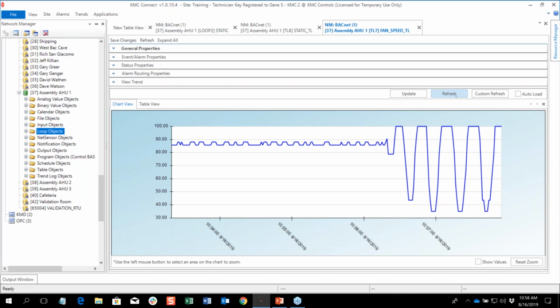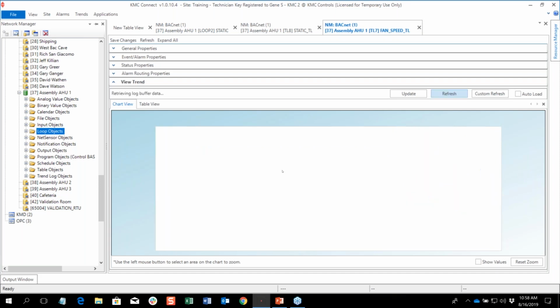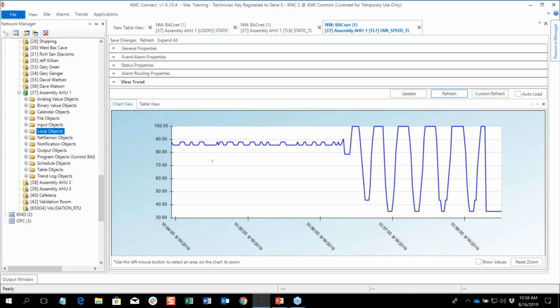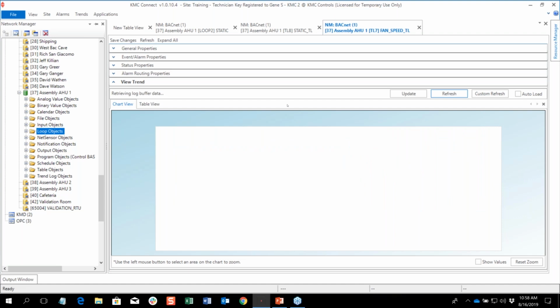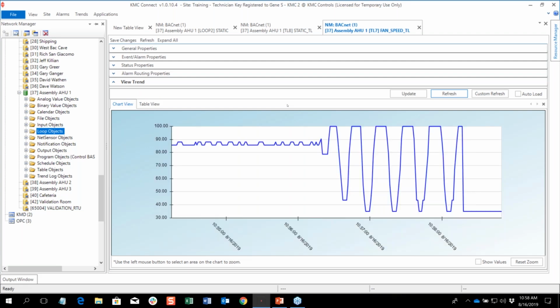Is there a good number to say on how much to change that proportional term each time? A third or a half? What's the guideline if I want to start changing that P term? Well, experiment, because you've got different equipment and it depends on how things are engineered.